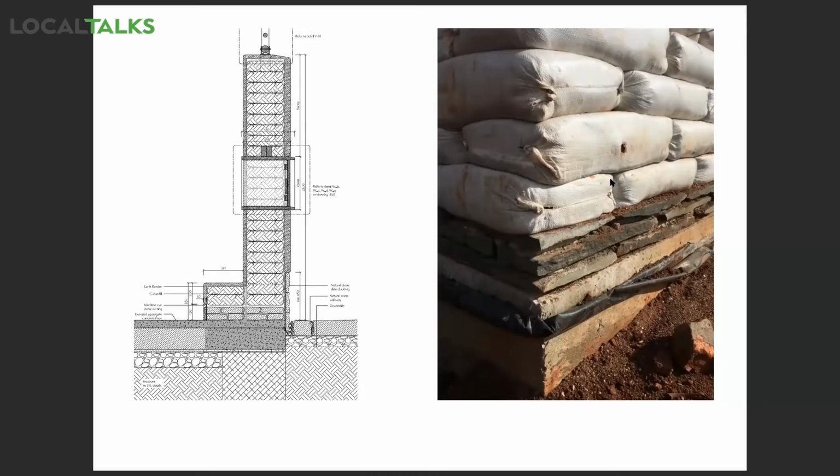So if you have good detailing, and you ensure that there's no water getting into this soil, you should be 90% sure that the termites will not bore through. Also in the finishing, the type of finishing that you choose: termites don't like lime. It has a very high pH. Insects don't like it. In fact, one way of preserving things is just to put lime.